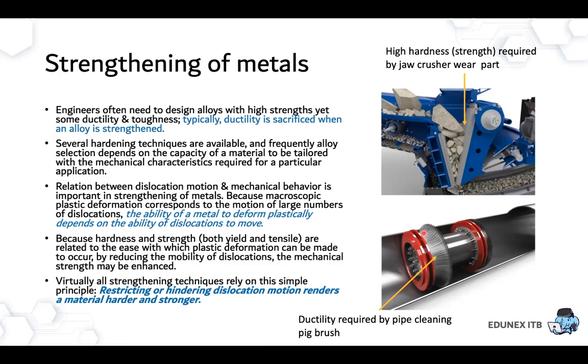Pigging is a type of equipment used inside a pipeline, with a pig launcher and a pig receiver. If you have a very long pipeline, 100 kilometers or 50 kilometers, and you want to clean the pipe, we send the pig from the pig launcher. It brushes around the pipeline and cleans all the mold, corrosion, and scaling.